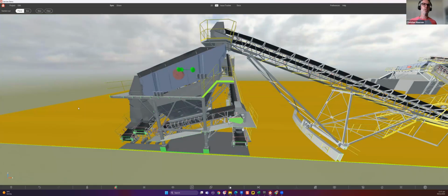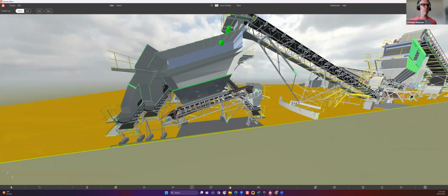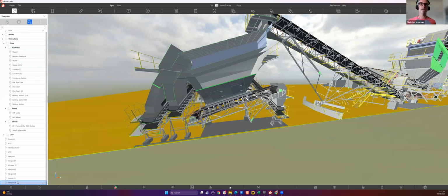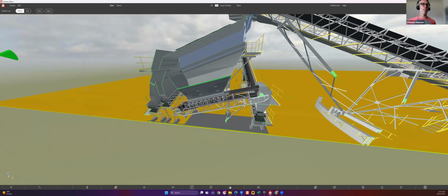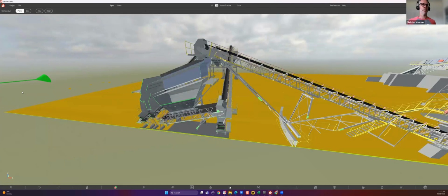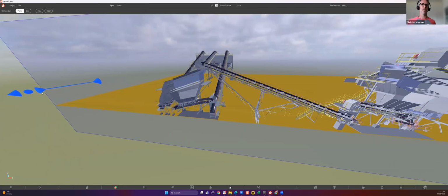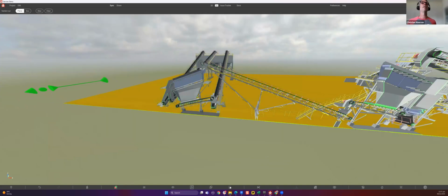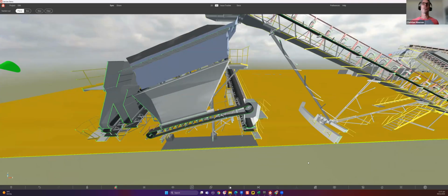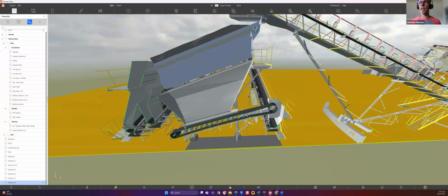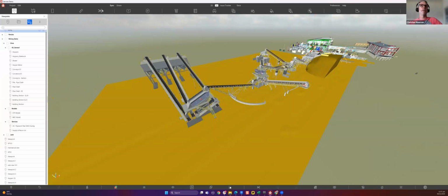Super useful in conjunction with your viewpoints. So now I can just click on my viewpoints down here, saved it in to my viewpoints over here. I can flick through it like so. If I want to change it, just jump back into my section mode. I can start to drag it further into the page like so. Just going to reset that, hit my home button, refresh all of that.